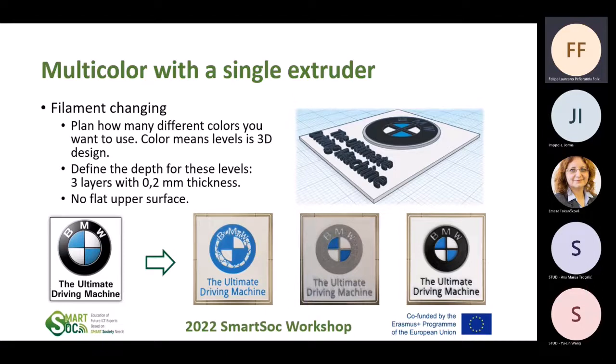You can hear it. The smallest layer height is 0.1, which is better. And if you still don't want to feel the layers, you can post-process. If you post-process, you can eliminate this feeling along the Z coordinate. And when we are talking about the XY plane, in this case, the smoothness is determined by the diameter of the nozzle. The diameter of the nozzle is 0.4 millimeters, which is worse.